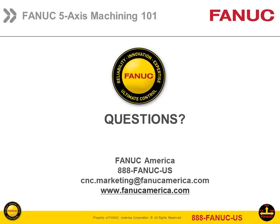Okay. Another one of our attendees would like to know, how often should I check the TCP parameters? Well, that's a good question. We would recommend in the beginning, initially set it up, and then 3 months later, check it again, to make sure your machine wears in, your ball screws wear in and everything like that.